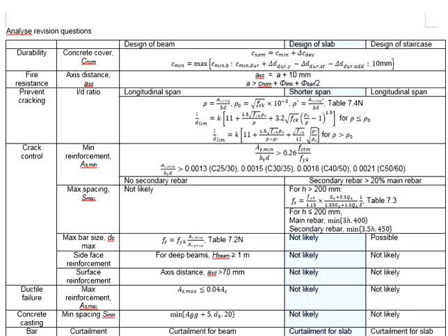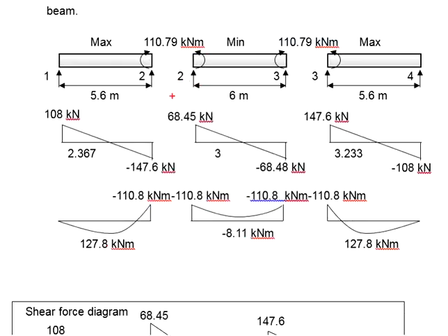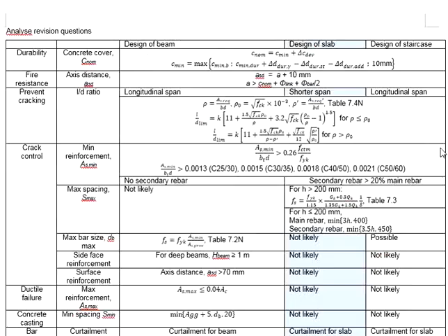If you find this difficult to remember, you can always sketch the member and imagine the deformations of the member when it is subjected to the loads. The bending direction of that particular member will determine the effective length that you use to compute the L per D ratio.